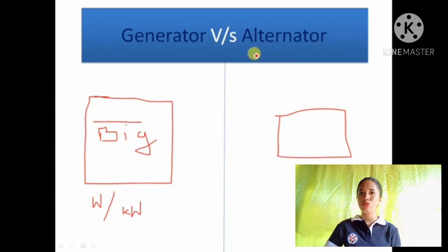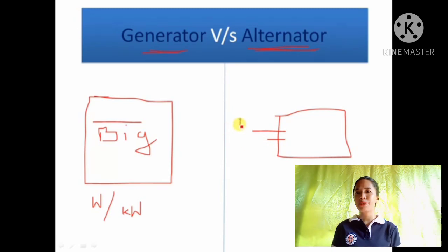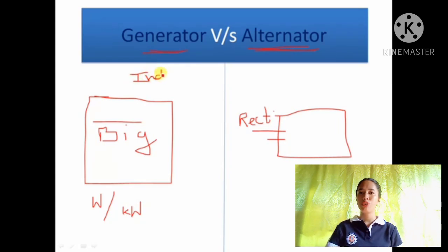That's why alternators are recommended for high power output, and generators are not that much used. If DC is required, nowadays rectifier units are connected to alternators. One exception is the induction generator, which is not that much used, but is used in windmills. You can check it on Google.